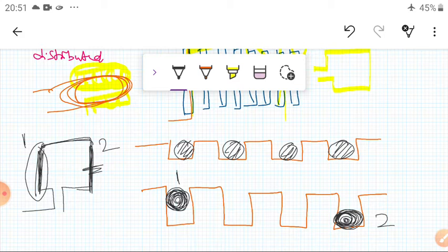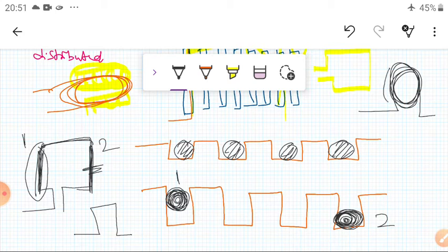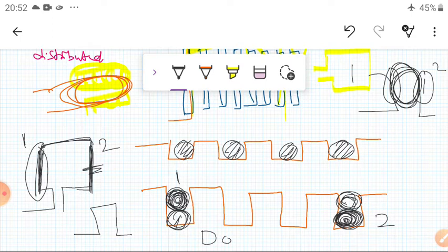You can take another coil. For example, this coil may consist of one conductor, or a number of conductors. This is one coil side and this is another coil side. This coil side is placed in position 1, and this coil side is placed in position 2. This is known as the double layer. Another coil will come here, so each slot consists of 2 layers. This is one coil side, this is a conductor, this is coil side 1 and this is coil side 2. Similarly, each slot consists of 2 layers.